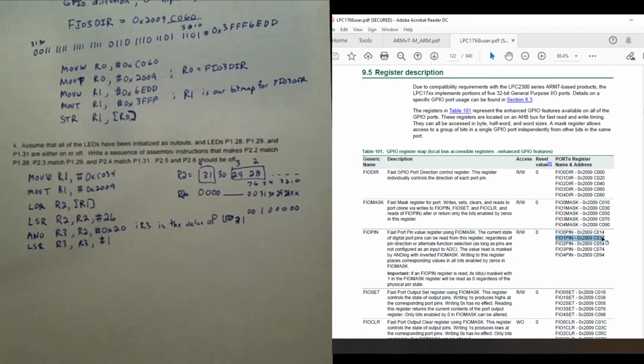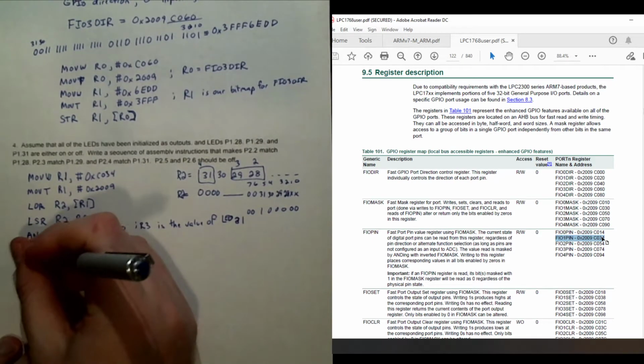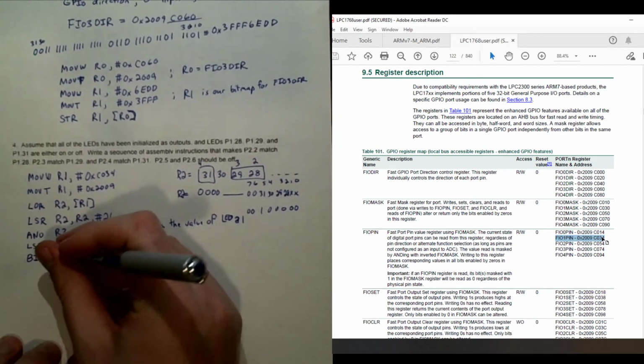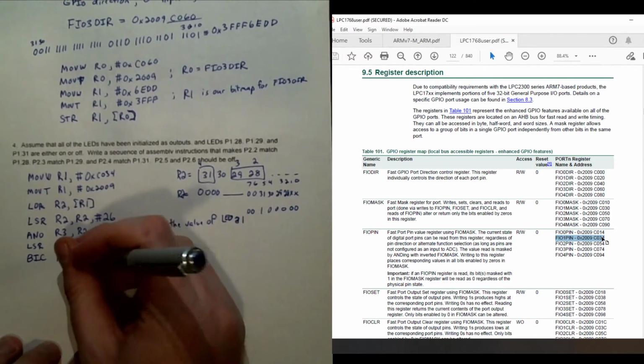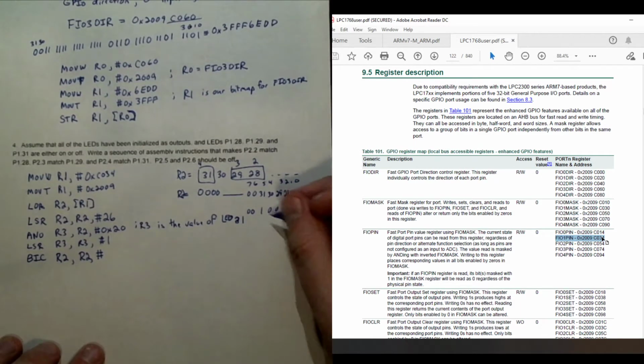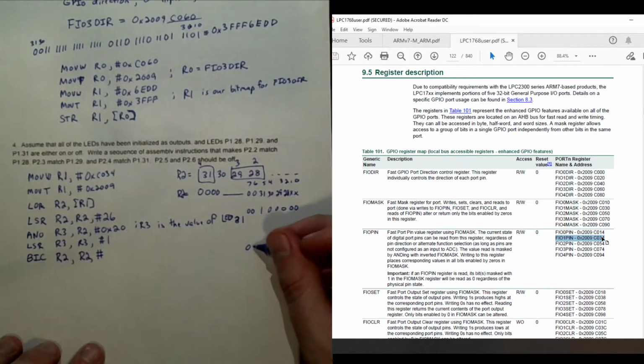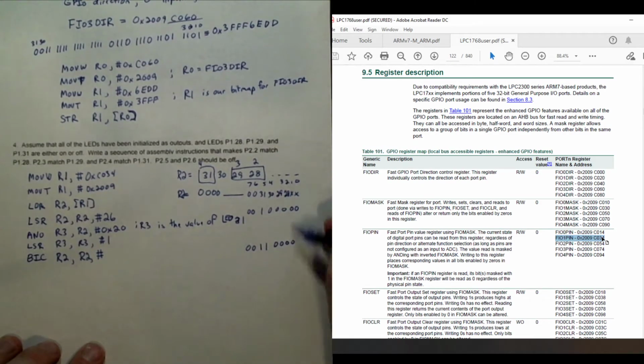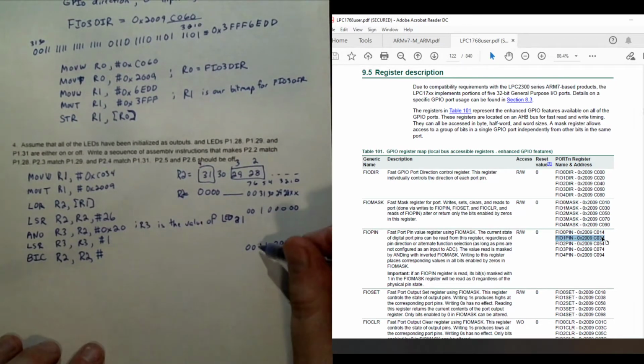So that sounds like a bit clear instruction. I'm going to do a BIC on R2, because that's going to be my final output, with R2 as input, and I'm going to use a bit clear field. I know 7 and 6 are 0. I want to make sure I clear out 5 and 4, and then I don't want to clear 3, 2, 1, or 0. I guess I could clear 1 and 0 for good measure, but I may want to just leave those anyways.